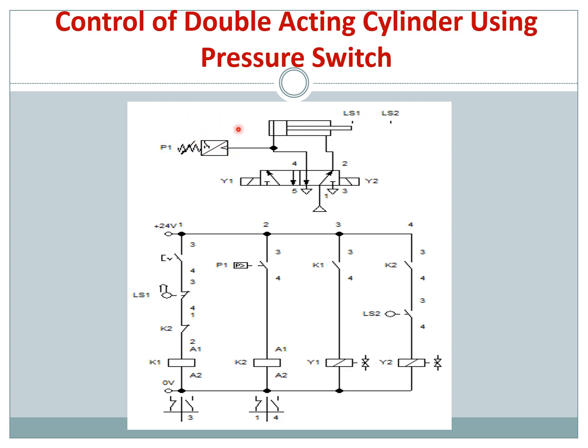But you have a pressure switch here. Meaning when your circuit reaches a certain pressure, only then will your cylinder start to extend. So when the pressure switch is activated, your cylinder advancement or retraction will be controlled. This is somewhat like a pressure regulating valve in pneumatics.